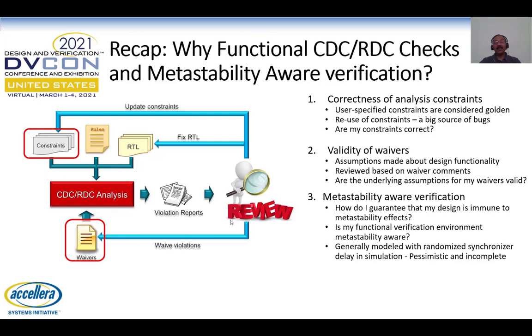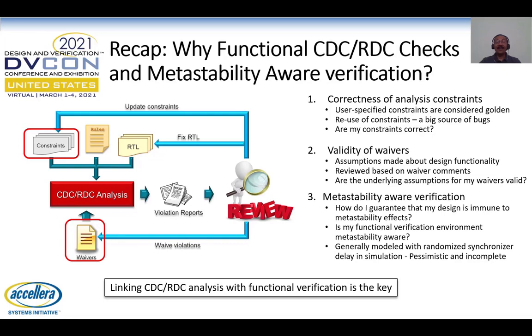And the third thing is to guarantee that my design is immune to metastability effect. And to do that, my functional verification environment should be metastability aware. Now, all these three things can be achieved by functional verification, which means linking CDC-RDC analysis to functional verification is the key to complete and comprehensive CDC sign-off.